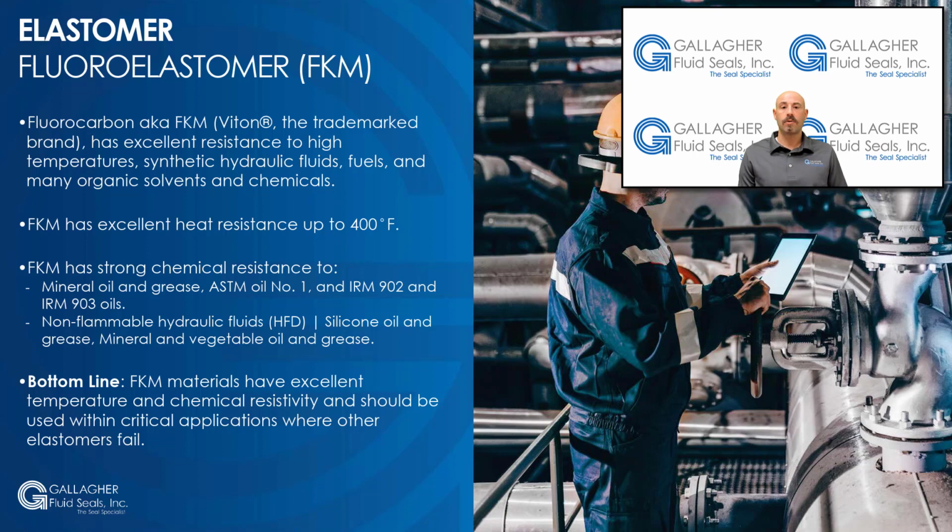Next, we'll talk about fluorocarbon, or Viton, which has excellent resistance to high temperatures, synthetic hydraulic fluids, fuels, and many organic solvents and chemicals. Similar to neoprene, the term Viton is a trademark brand, and the technical term for the base elastomer is fluorocarbon, or FKM.